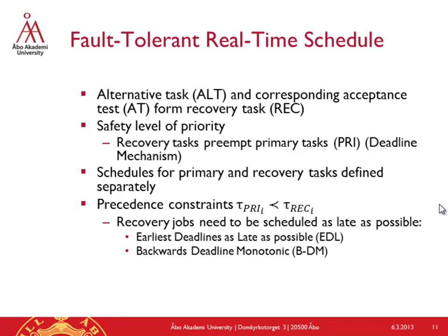One such unwanted behavior might be a task hang. If the execution of a specific task takes too much time, or the task instance basically hangs, this situation should be mitigated somehow. To mitigate it, we propose to use preemption and a special priority arrangement of tasks.